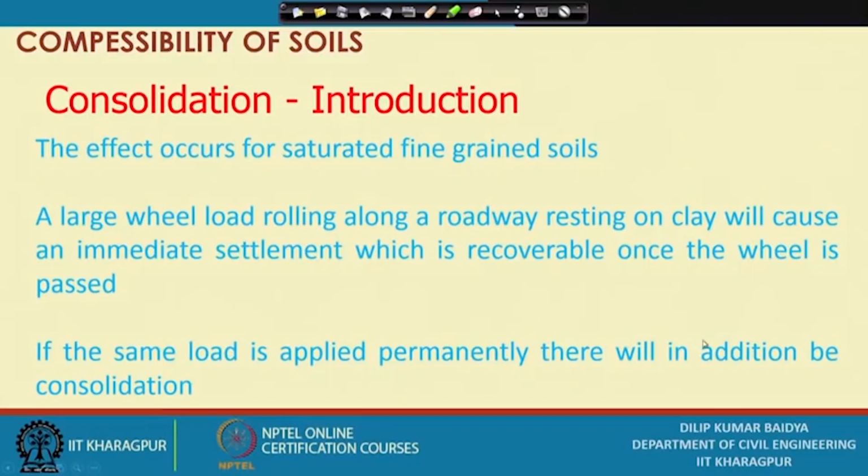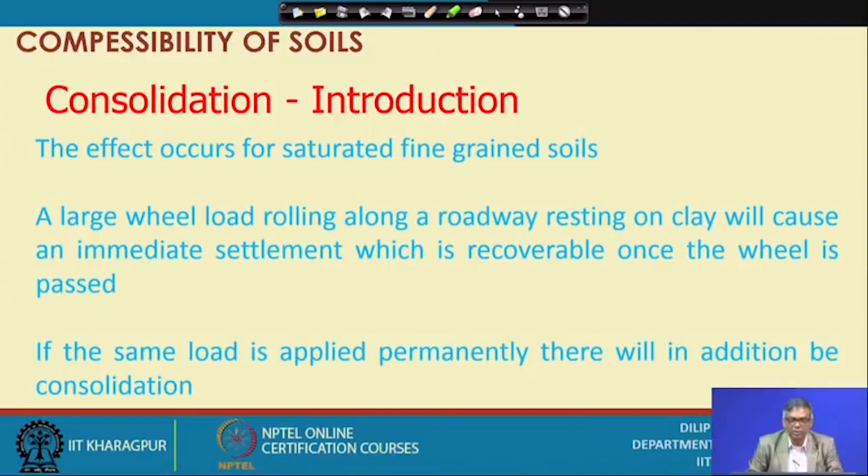As an introduction, what I can say is that the effect occurs in saturated fine grain soil. That means consolidation happens for saturated fine grain soil, and a large wheel load rolling along a roadway resting on a clay causes an immediate settlement which is recoverable once the wheel has passed.